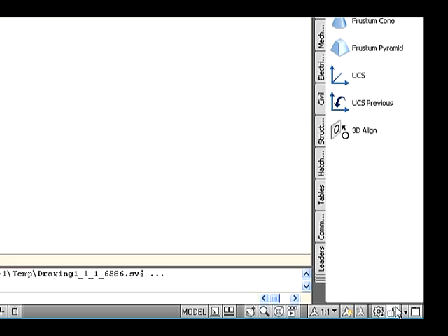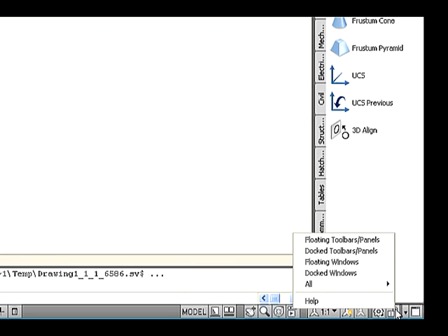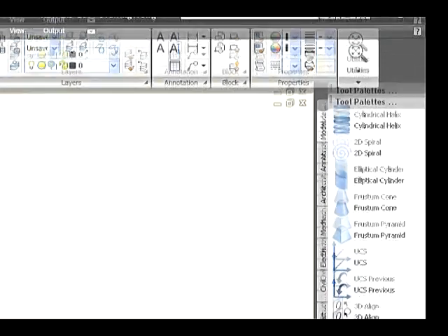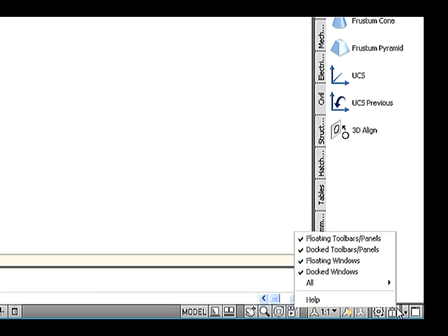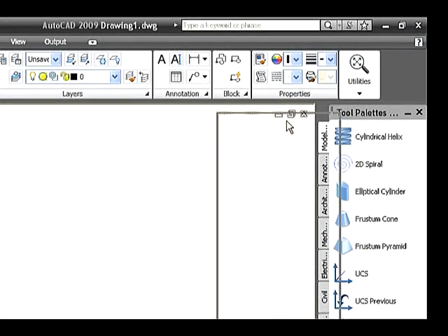Where did I leave that Properties palette in AutoCAD? Well, you'll never have to ask this question to yourself again. AutoCAD 2008 lets you lock toolbars or palettes in position, so you'll always know where they are. To lock the toolbar palette positions, right-click the mouse. A drop-down list appears where you can select All and select Locked. Now, the toolbars are locked and you can't move them. To unlock the toolbar palette positions, select the Unlock option instead of Lock.